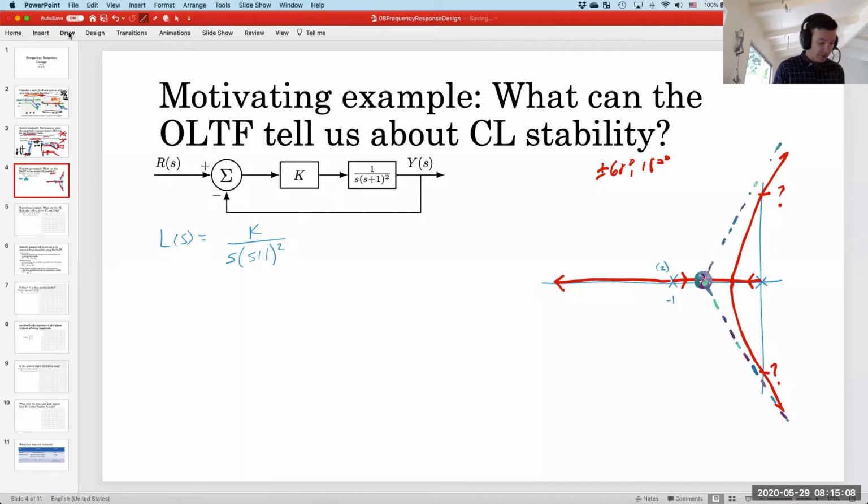So the technique that you've learned so far is set the open loop transfer function equal to -1 and evaluate it at j omega. That would make sense. So L, when s equals j omega, has to be -1. So that would mean this equality is the definition of a closed loop pole, and this equality means that closed loop pole is on the imaginary axis. Okay, so that would give us the crossover point. Okay, so let's go ahead and do this.